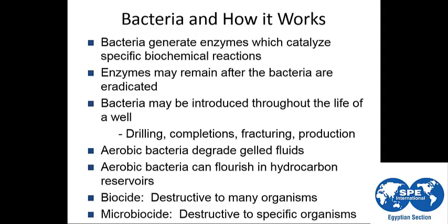Also, we are using the biocide to prevent any organism from existing inside the frac fluid, and we put the biocide inside the tanks before filling with water. Because, as we said, bacteria create enzymes, and the enzymes work as a breaker.